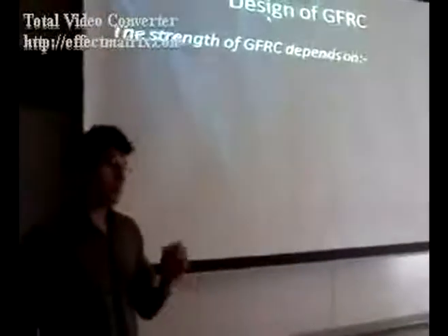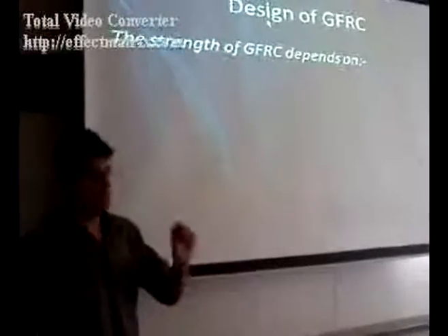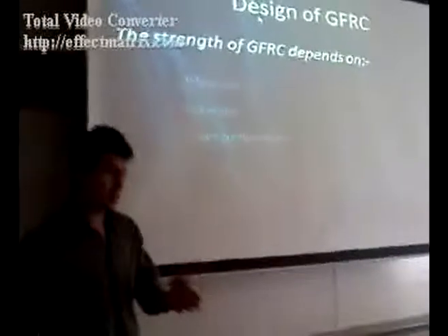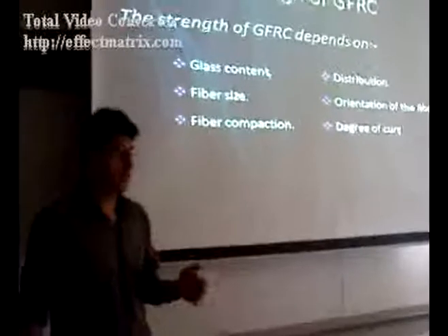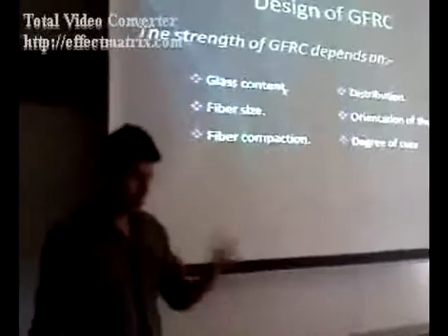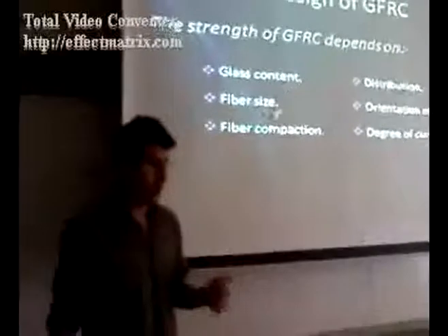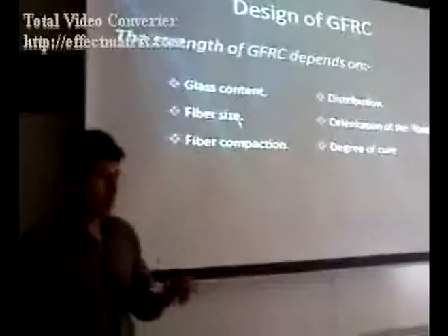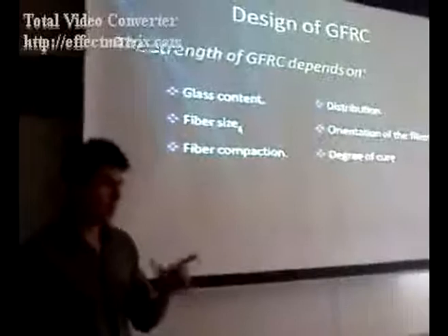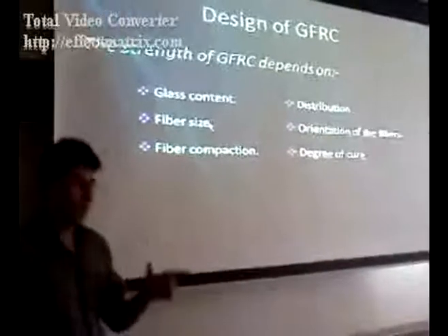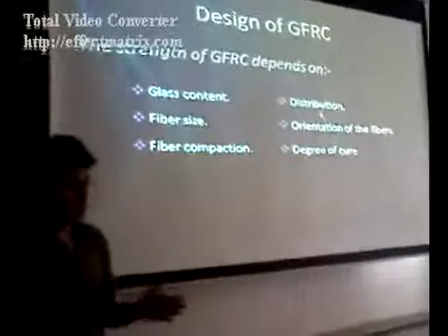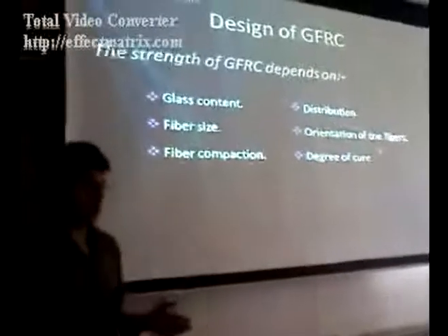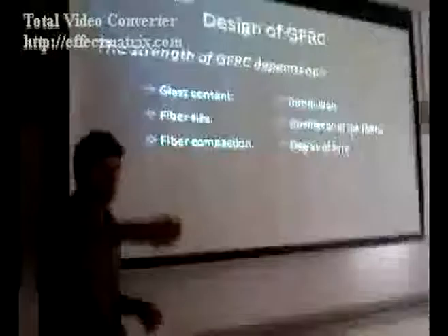Now, the strength of the GFRC itself depends on several things. The glass content: a higher percentage of glass fibers makes it a lot stronger. Fiber size: the longer it is, the stronger it is. The fiber compaction, distribution, and orientation of the fibers, whether I'm spraying like this or like this.